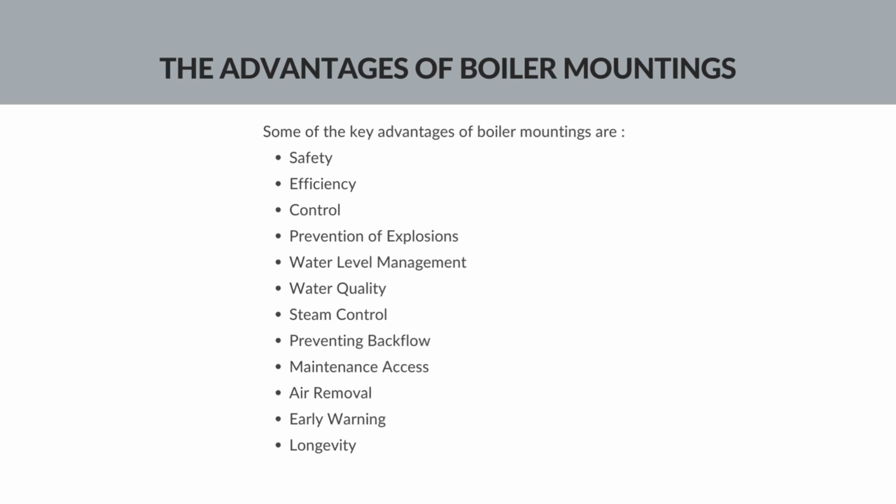Fourth is prevention of explosions. Safety valves, crucial boiler mountings, release the excess pressure to prevent explosions, safeguarding both the personnel and equipment. Fifth is water level management. Boiler mountings like water level indicators and feed check valves help maintain the correct water level inside the boiler, preventing damage and ensuring efficient heat transfer.